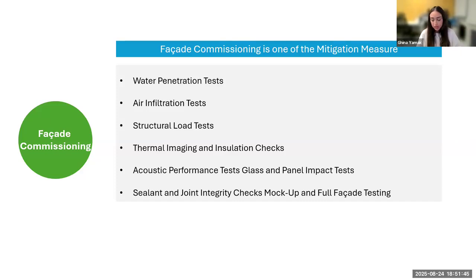So too many parameters, and you run the simulation considering the building location, the weather, the country, the geometry, all that. You run the simulation and you get some results, but do we actually trust those results 100%? How can we test that? Commissioning will tell you if what you designed is okay or not.